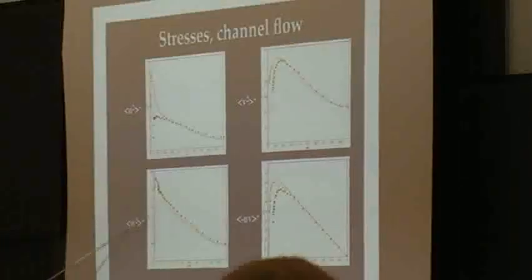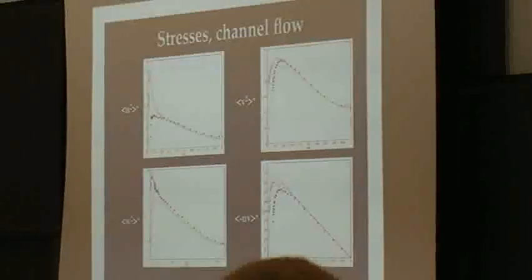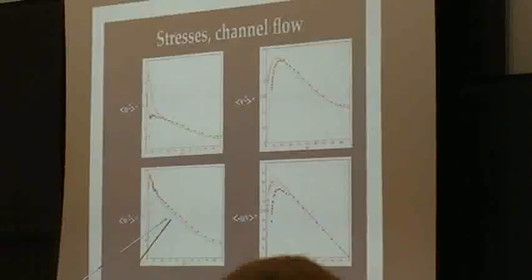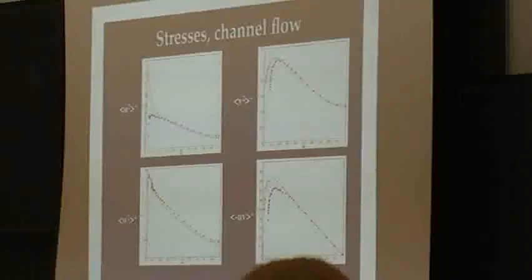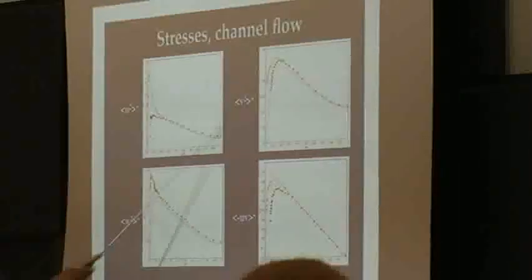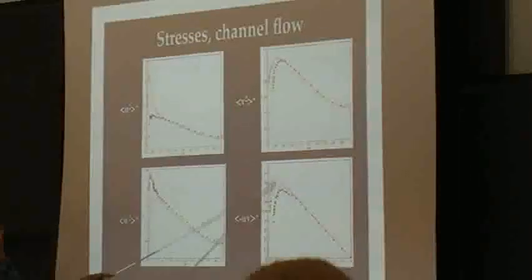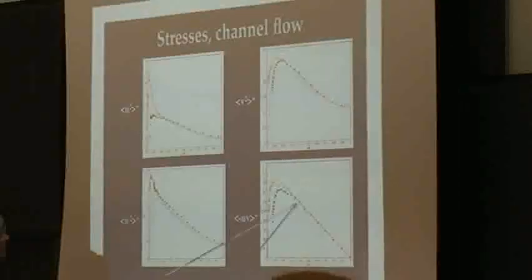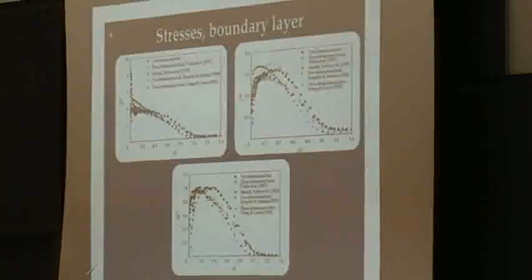And in fact, when we looked at the W squared, where we would expect part of this energy to go, we do also find a reduction, at least in the DNS. And you see that this reduction extends all the way to the center line. I have no explanation for why this should be more sensitive than the other two, but this seems to be more sensitive. And we get the reduction in the shear stress near the wall. In the outer layer, very little effect, because you have to end up with a linear distribution.